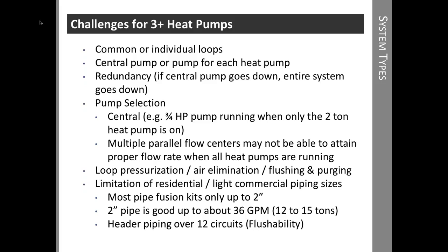Pump selection is important. A central pump, if it's constant speed, can be problematic if only 1 heat pump is running, especially if it's a small heat pump. We might have as many pump watts as heat pump watts. The other issue with that type of situation, if we have multiple parallel flow centers, is that we might not be able to attain proper flow rate if all the heat pumps are running. So pump selection is pretty important.